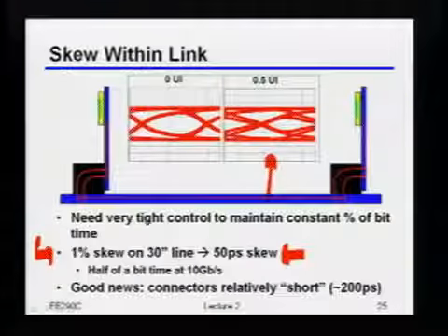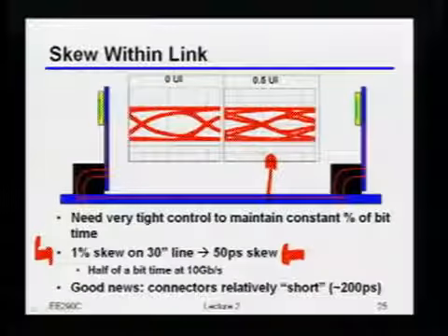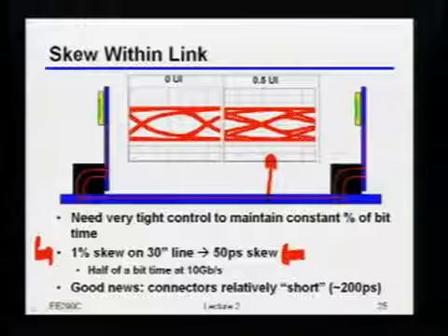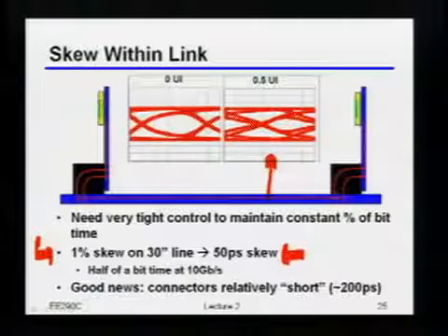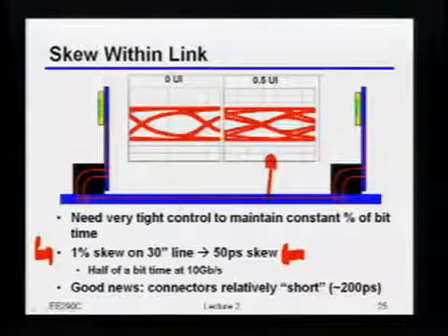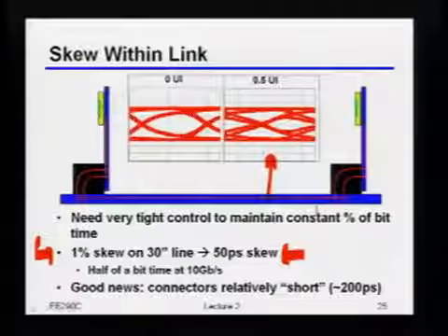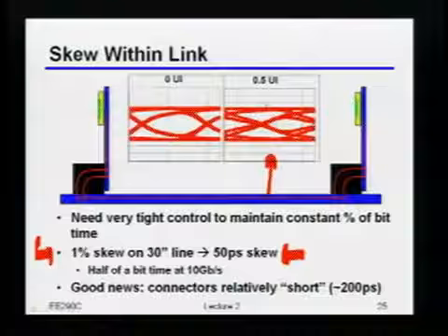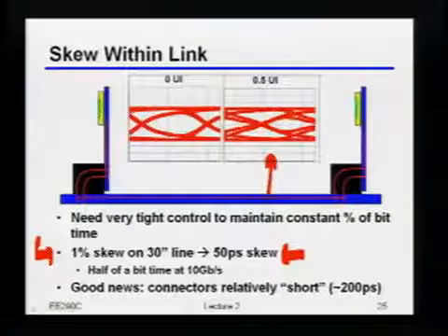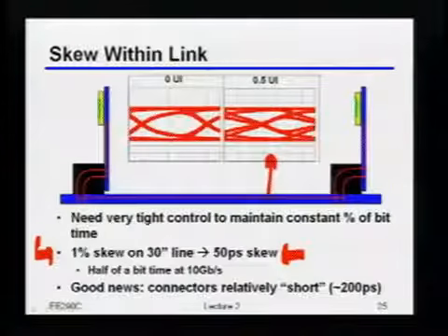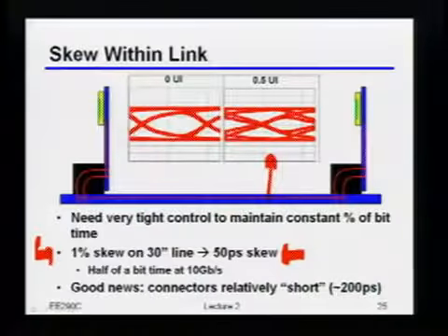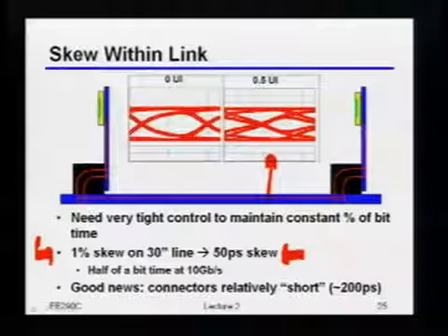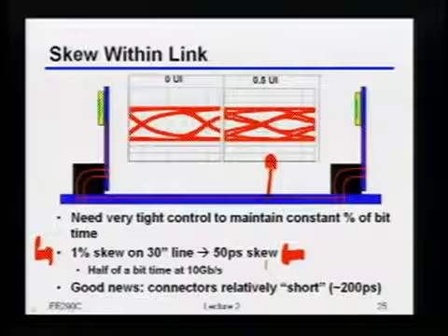So that tells you that, obviously if people really are going at these 20 plus gigabit per second kinds of rates, they're doing a really good job of keeping the skew on these big, long PCBs really, really small. Because if it wasn't, then you'd have really, really bad time actually just getting through on anything on the other side. Obviously, as you said, your common mode rejection and everything else is also a lot worse, but I think actually this is one of the even bigger issues.